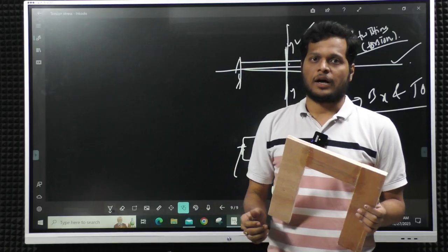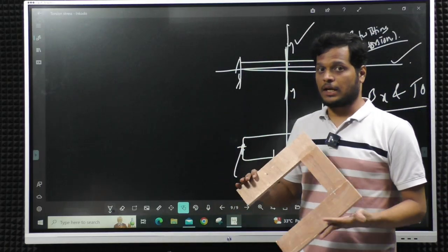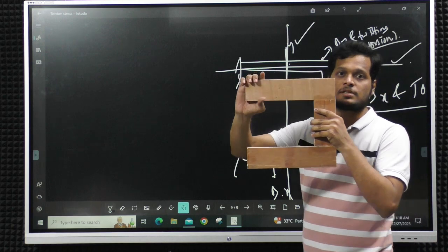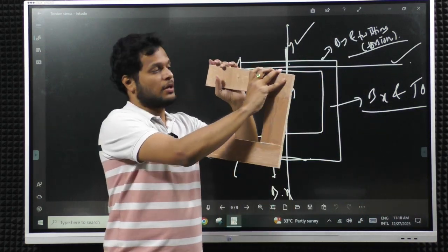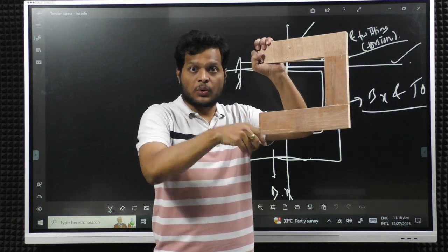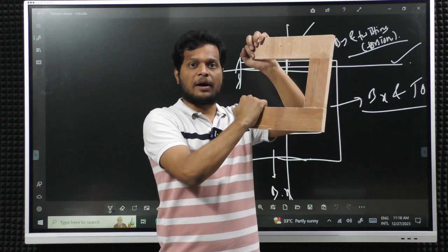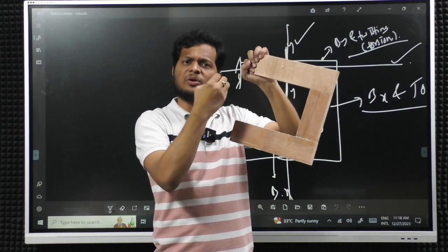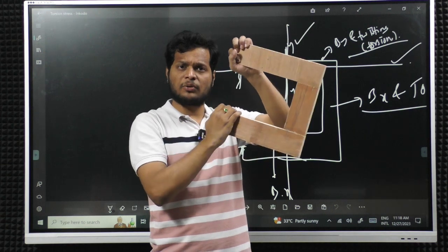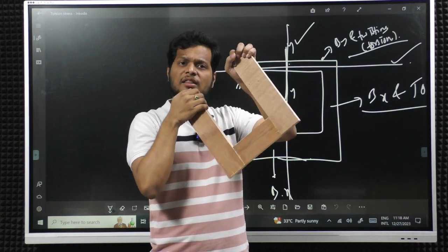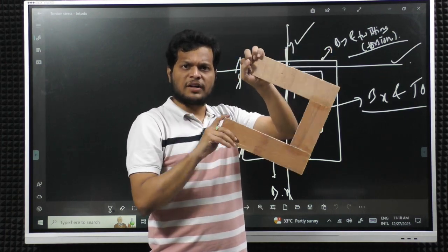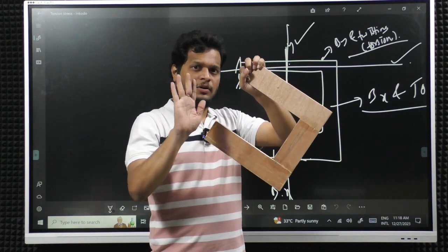Okay. Now, I will show you this example physically. See, my frame is given like this, okay, which is fixed at this end. Okay, means I am holding this frame like this. Okay, I am folding this like this. In the first case, how is my load? It is downward towards the gravity. I am applying like this. So, if I apply like this, let me allow some deflection to feel the bending. Okay, I am applying the load downward. You can see there is no twisting anywhere in the beam. Okay, everything is simply rotating about the cross section. Okay, if I allow the deflection, you can feel that, right, only bending.